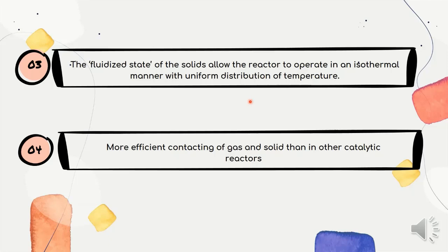So the mechanism of the fluidized bed reactor itself, or the fluidization, leads to the isothermal condition, and the temperature is the same at all parts in the reactor. Thus it will lower the risk of hotspot and runaway and thermal instability that may lead to serious problems.